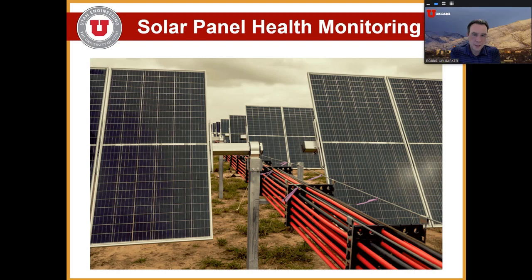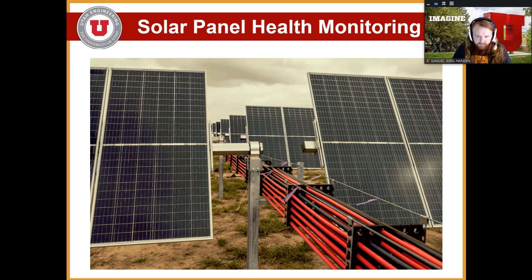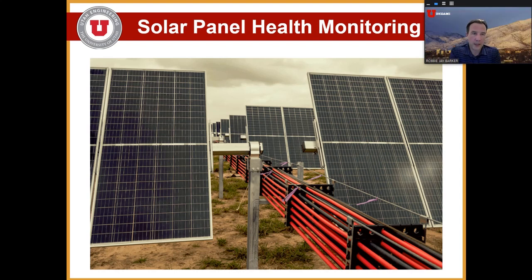And to tie this back into why we were talking about the importance of SSTDR when it comes to solar panels and solar fields, all of this comes down to impedance and impedance discontinuities, fault detection, things like that. And so understanding how SSTDR responds to impedances such as capacitors or panels under varying illumination and weather effects is important if we want to help these large solar installations move forward in an economical way.